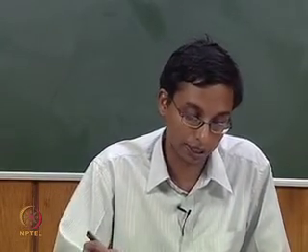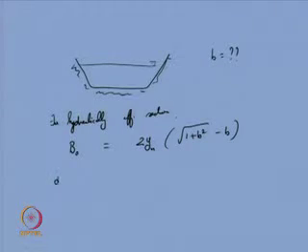Let us see how that is. Your wetted perimeter here again has to be differentiated with the channel side slope, and you have to see that that is the minimum one. So, if you equate dP by db equal to 0, what will you get? You know what P is?